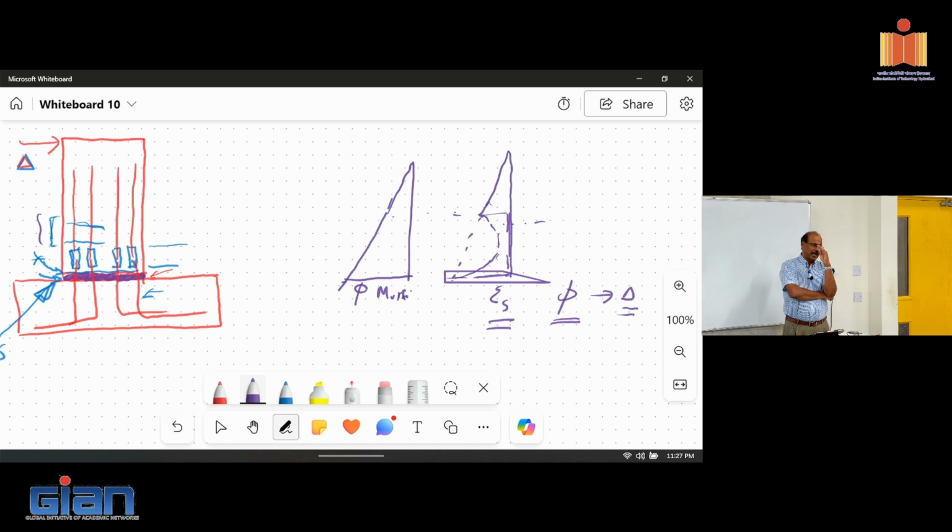But the wall crack distribution will be better by doing it. But the precasters then have to have the bar sticking out to go into the foundation, right? So you have to pick and choose which is going to be convenient. I think grouting the couplers within the wall panel is easier, with an outlet and inlet, than trying to reach the foundation. So there are advantages and disadvantages. We actually looked at putting it in the foundation versus in the wall panel, and we did see some differences in the behavior, but it's an emulation option whether you choose it or not.